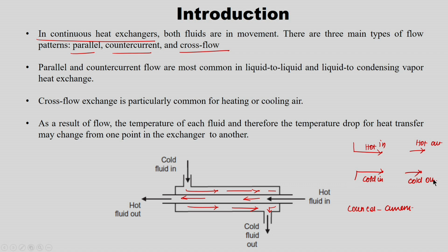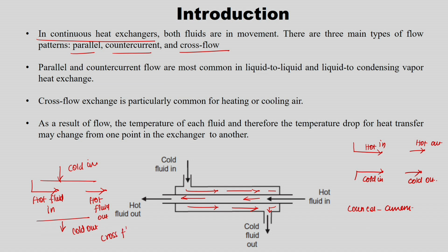Right. Cross flow is nothing but your hot fluid in and your hot fluid out, inside the tube. Your cold fluid will be perpendicular to the hot fluid direction. So this is nothing but your cross flow. So this is counter current flow, and this is co-current flow.